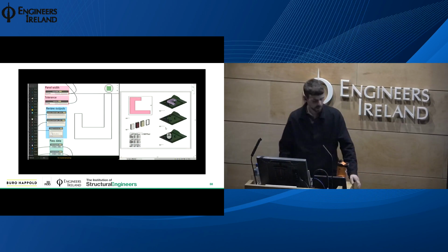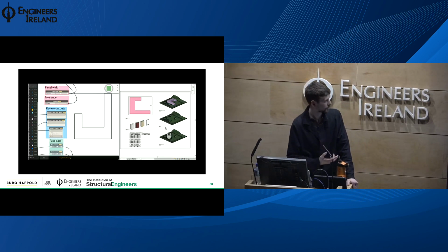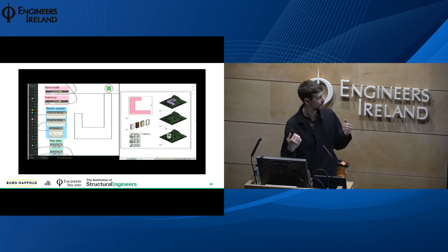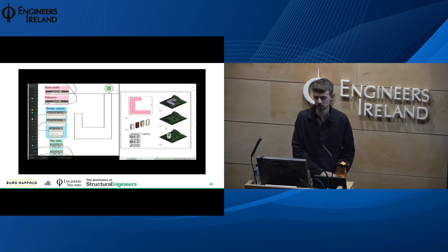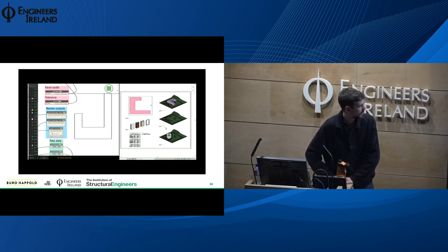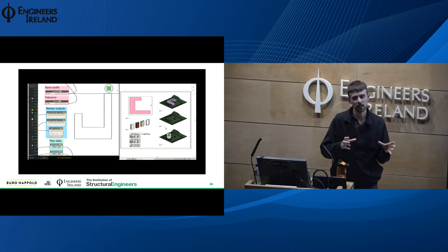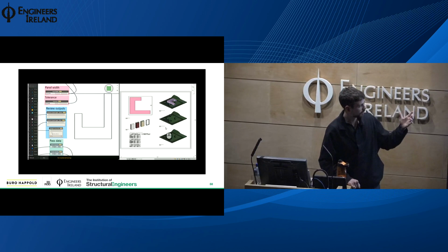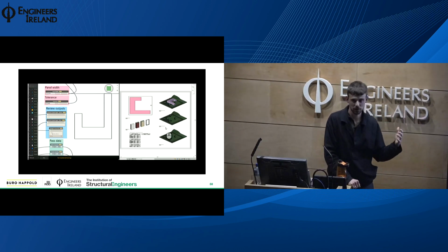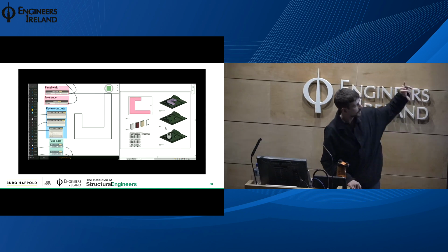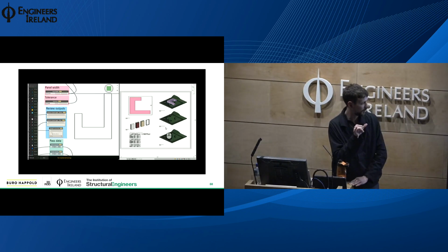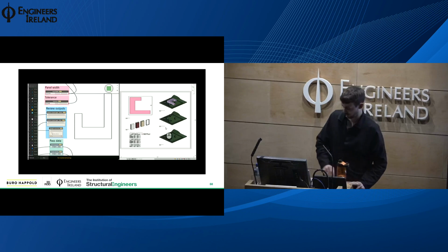And then just a video about how that looked in terms of the realisation of the project. Architecturally, we wanted to be able to manipulate a building's mass with the understanding that you were going to panelise the facade components later down the line. So rather than having 60 unique different panel sizes and types, we wanted to be able to manipulate a mass based on a regular component module. It could have different materiality, but essentially the base frame was to be the same system of regular modules, so that each elevation could be divided exactly by the length of one facade module.